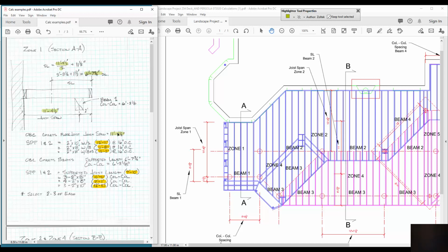And that allows us to look at the Ontario Building Code charts. We know that this is the number we're trying to achieve as a minimum. And these are the 3 values. You want to find at least 2 or 3. And these are the 3 values that I found: 12 foot 11, 11.8, 12 foot 2. So that's how we calculate the joist for each one of the different projects.